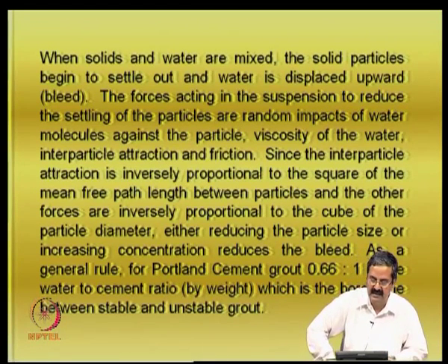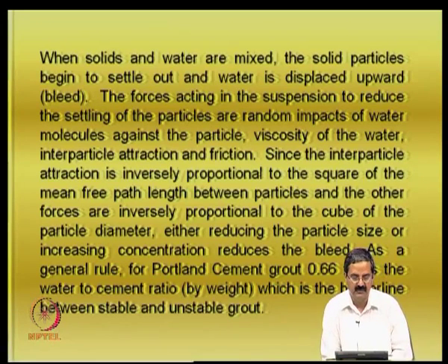The forces acting in the suspension to reduce the settling of the particles are random impacts of the water molecules against the particle, viscosity of the water, interparticle attraction, and friction. See, in the case of grout, imagine that you are doing a hydrometer test. A hydrometer test is a simple example of a slurry. So the forces acting in this soil suspension or grout suspension, we try to characterize in terms of Brownian motion, but here the impacts of water molecules against particles, viscosity of the water, interparticle attraction, friction.